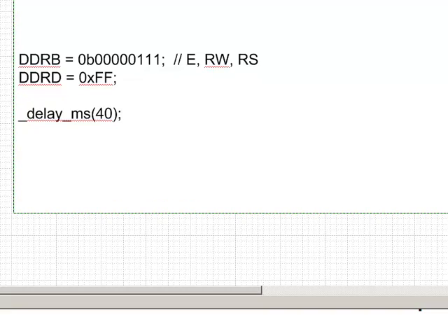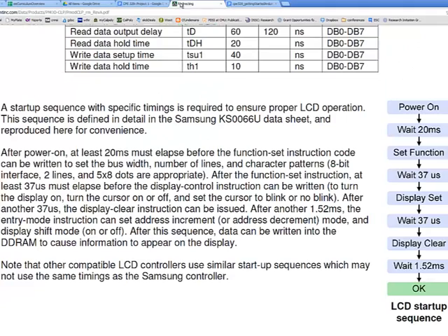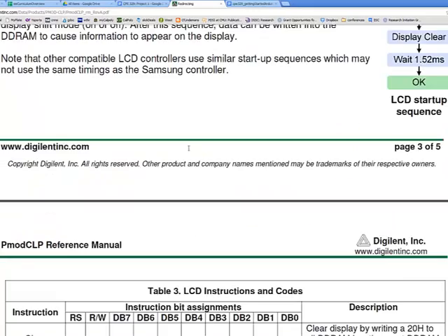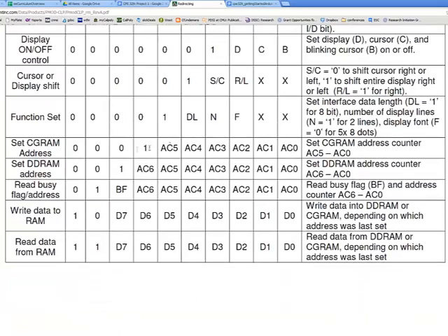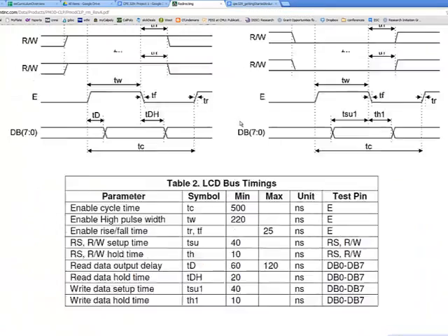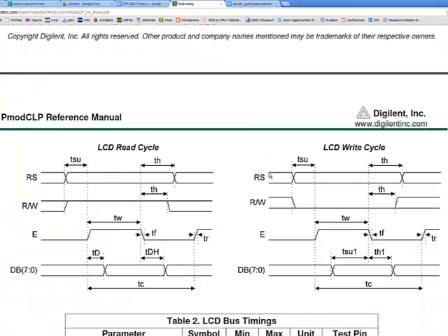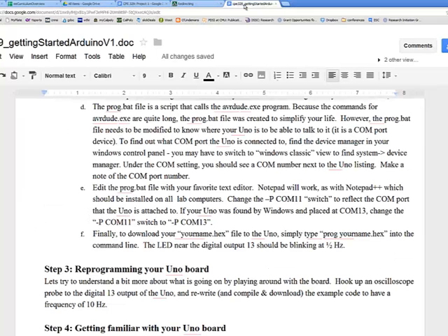And then I'm going to do the function set. Again, we looked at this table here, and it turned out to be 38 hexadecimal, if you remember correctly. And that's what's going to be on the data bus when we do this waveform here. So first I need to make RS and RW go low.